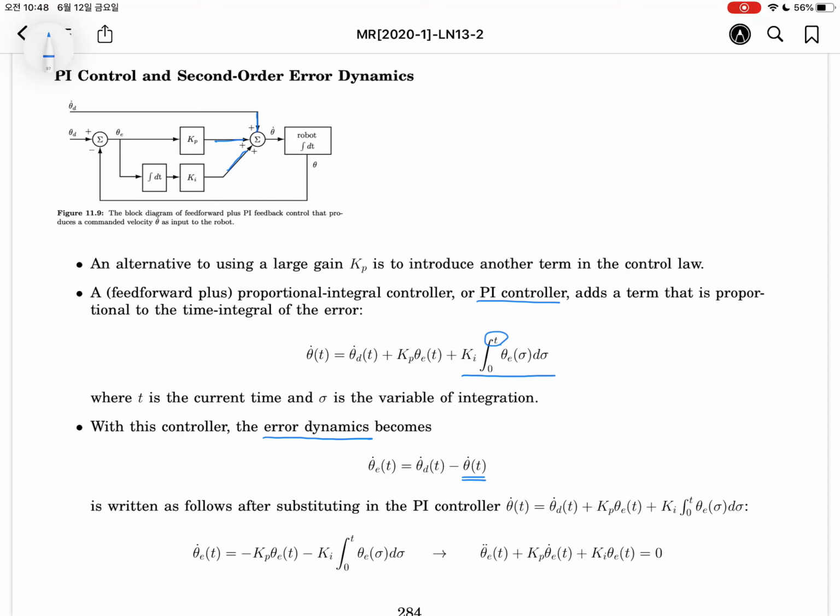for the velocity control input, so it will be applied to here. Okay, in the case of, as mentioned before, if your amplifier is determined by using the velocity control input, then we should make the control input in the form of velocity. Okay, so this is a control input. So it will be applied. Then you have this equation: first order, zeroth order, and integration. So we will apply one more time derivative. Then we have a second order differential equation.